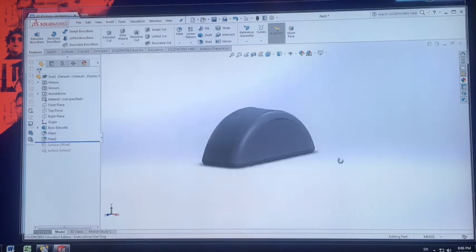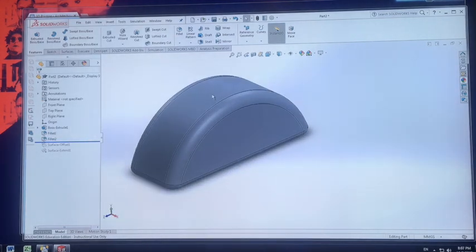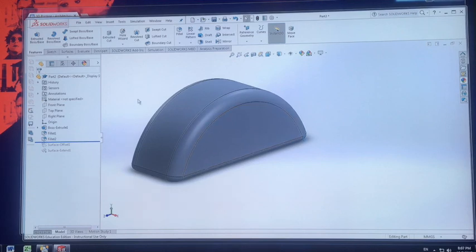The first thing I'm going to show is just surface offset and surface cut. So this is my shape. Now let's say for whatever reason I haven't been able to shell it, but I want to remove a bunch of material on the inside. Now this can happen if your object has a lot of small fillets or cuts or angles, and the fillet doesn't want to compute, okay? Or it's just a bad surface.